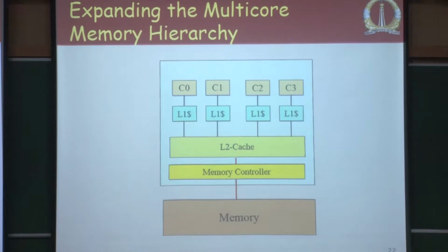Now, let us go back and talk a little bit more about stacked DRAMs and DRAM caches. Remember, in one of the earlier diagrams I talked about embedded DRAM, which is some kind of DRAM on a processor, but that is a different kind of DRAM. I am not going to talk about that, but something very similar is what is called a DRAM cache, where I would build a DRAM on the same chip itself.